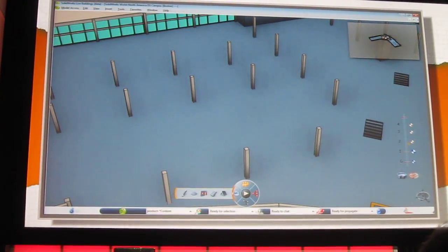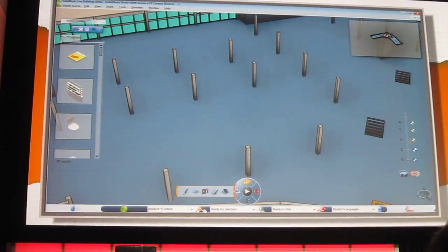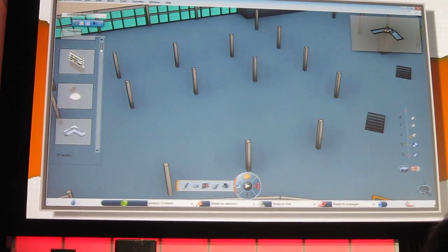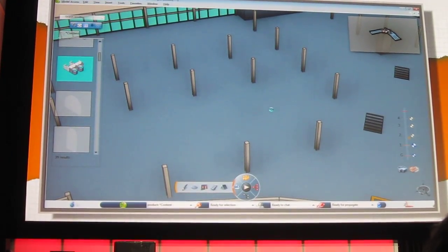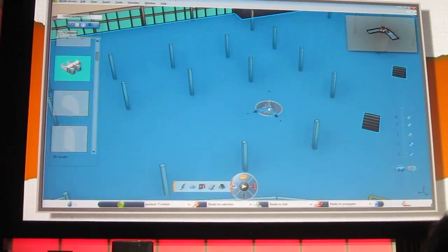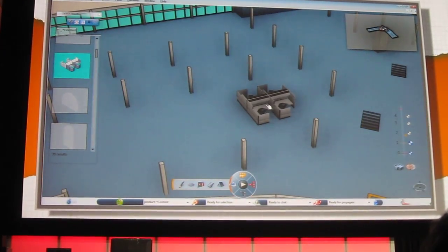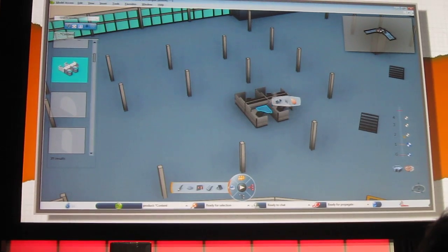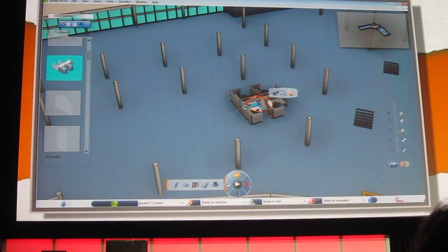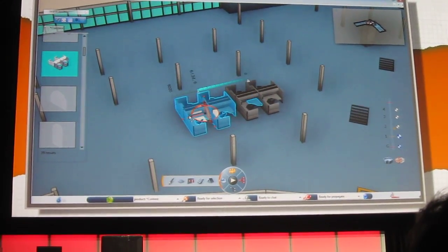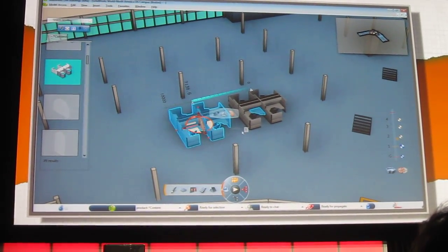And it's going to give me a number of items that we're going to use within this building. So we'll take a look at the cubicle and just drag and drop that into the floor space. It uses a concept similar to SmartMate, so it knows exactly where it's supposed to go. But if we want to make a copy of that, we'll simply use the triad, as we saw previously, and just drag it over to the left. So you can see very quick, very easy, a very nice conceptual tool for designing office space.